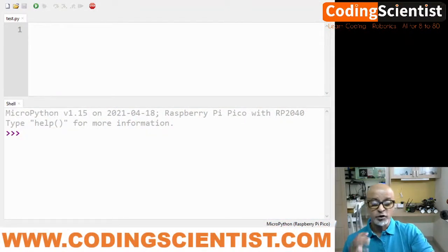So basically MicroPython adds a hardware specific module such as machine. Okay, machine is a hardware specific module, or you can call it a library, which is inbuilt within MicroPython that you can use to program your Pico. Now what it does, we will be creating pins, a machine.Pin object. It's an object to correspond with the onboard LED or any of the GPIO pins, 25 different GPIO pins, right?